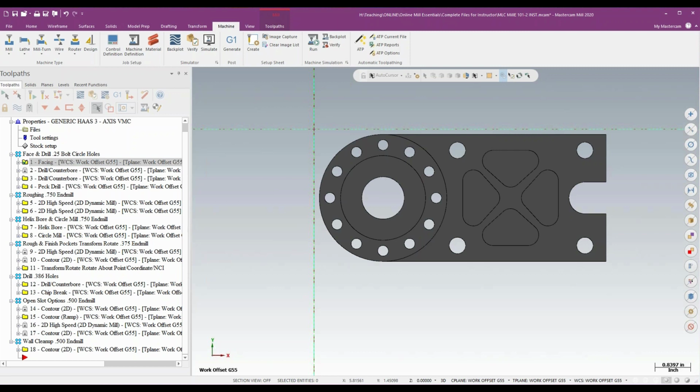And the first thing we're going to look at, and this is one of those things that's really easy to miss if you don't know that Mastercam does this, is taking advantage of Mastercam's use of tool data when I'm programming. I've just got a generic part open that's already been programmed, and I'm going to show you how to access certain factors of tool data to just make things go a little quicker.